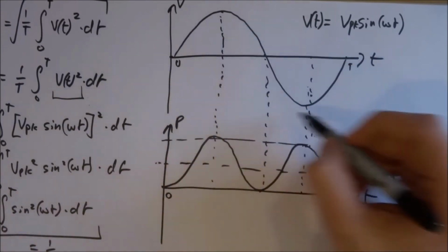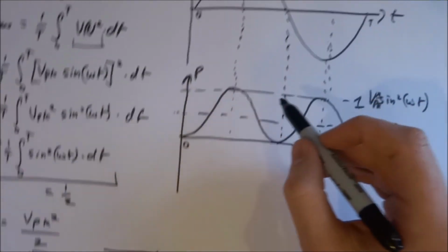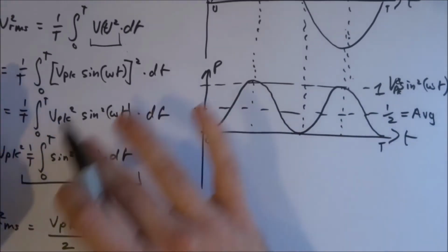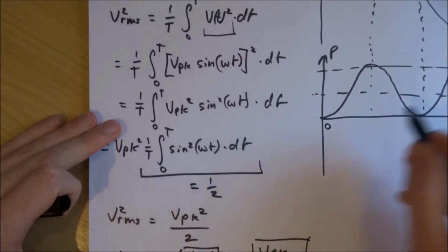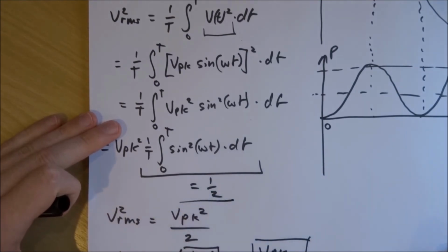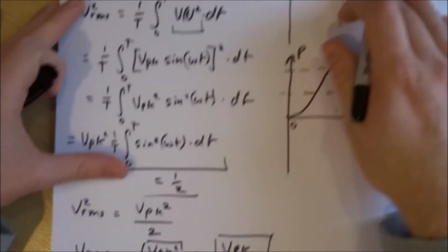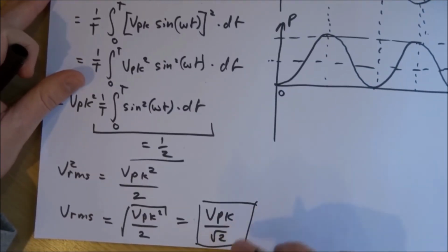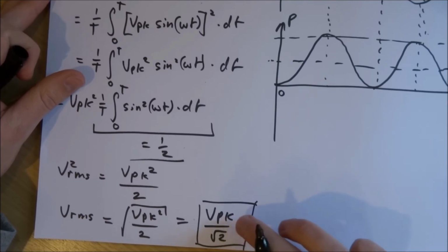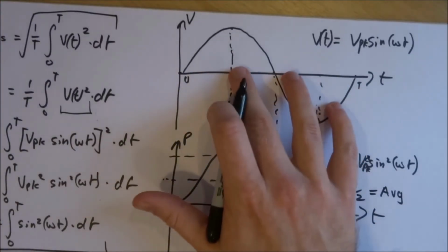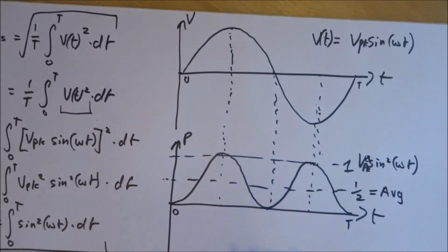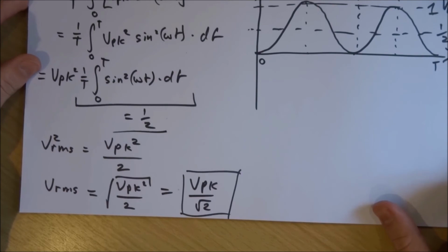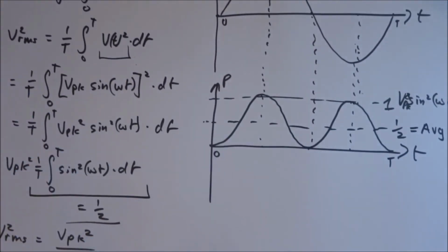It'll only work on a pure sine wave because the square of that sine wave looks like this, and the average comes out to 1/2. And this whole thing here, as you see, assumes that the square of the sine wave function collapses to 1/2. If this is not a sine wave, then this is not 1/2, and this whole assumption breaks down. So you may still get an approximate value using this, but the more distorted your sine wave becomes, the less accurate the answer from this function will be. And I will demonstrate that using the simulation.